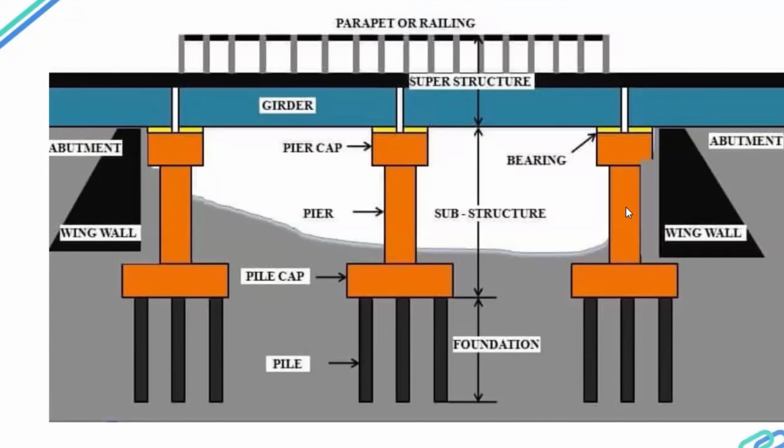Pile cap is relatively a standard type of structure. We go normally with rectangular pile caps, which take the load from the superstructure and the substructure, and transfer it to the piles. But normally what happens in these pile caps also, there are quite a few challenges that we face during the construction. When the contractor actually goes on to do the piling, many a times they encounter various utilities. For example, the underground cables which are running through, and they might also encounter other utilities, the pipelines,